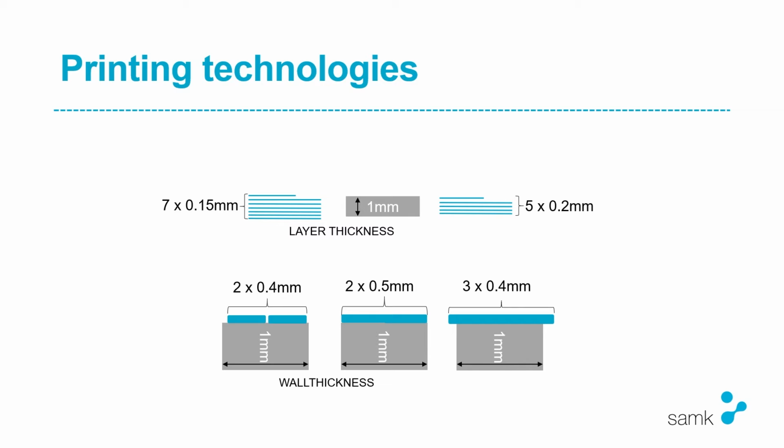It will have to either over extrude the material so it achieves 0.5 millimeters for each line, or it has to create a gap between the 2 lines so it can push infill there or just keep it empty. Basically, again, if we want to optimize, we should have a wall thickness that can be divided by the nozzle size, and the result should be even.